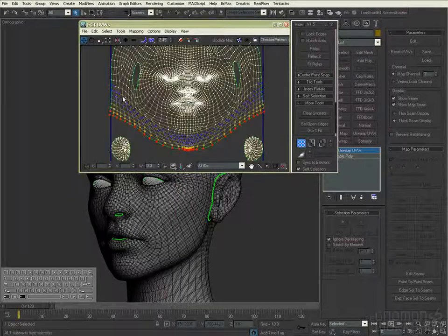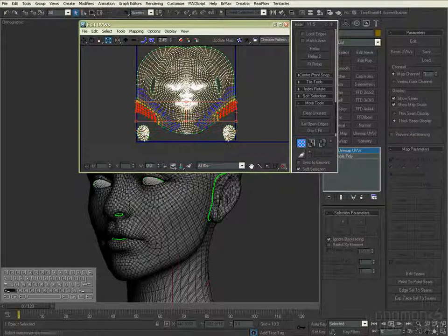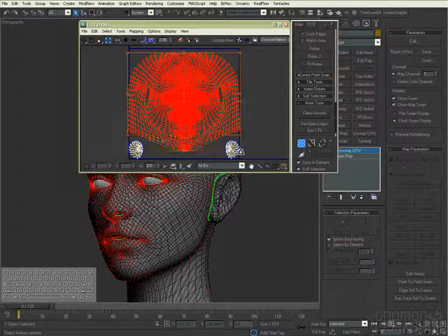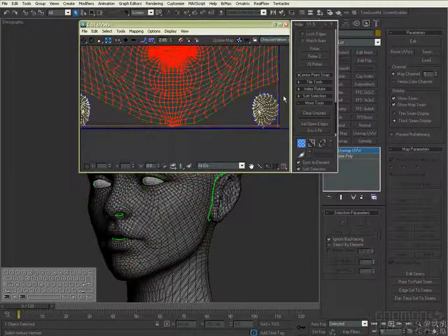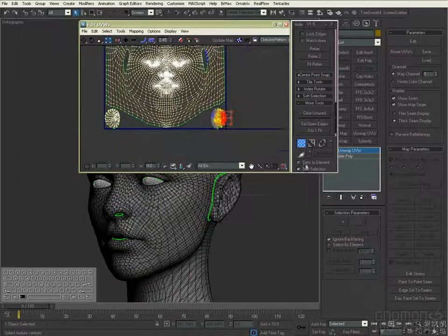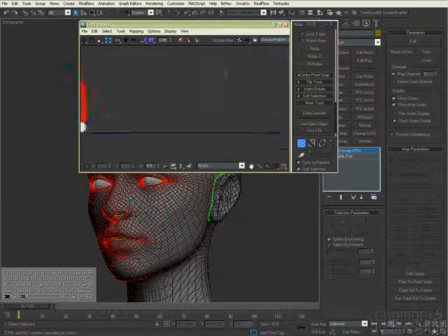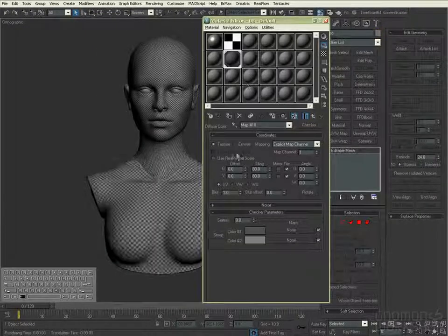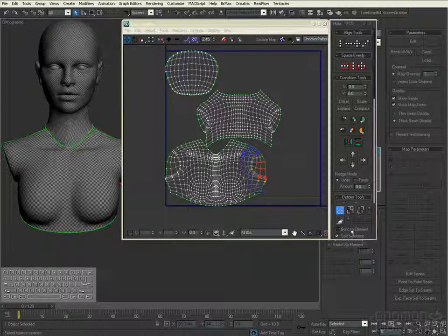And right now, the corner of the face is actually exceeding the boundary of the UV space, and that will also crash ZBrush and BodyPaint. So make sure that you are within the boundary, one or two pixels smaller than what you need to be. It will be very minor, not using the space, but it will be safe to export later on, and you won't have any problems. Make sure to move in a little bit. Yep, checking on four corners, and once you're happy, collapse it. That will bake the UV into your mesh. And then before you start another section.